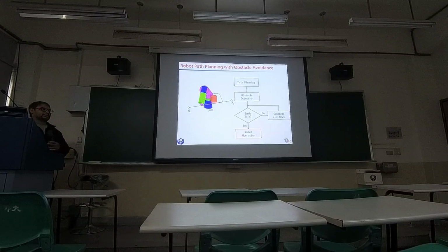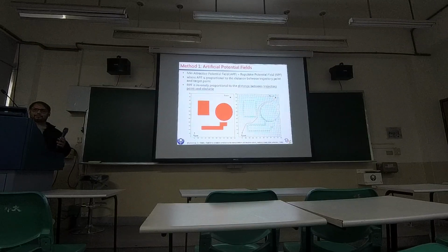Later on we'll discuss today's methods, traditionally like the gradient method, Newton's method with Lagrangian minimization principles, or there are different other methods. First one is the artificial potential field for path finding from the start position to the goal position. It uses the relative repulsive and attractive potentials within the environment.